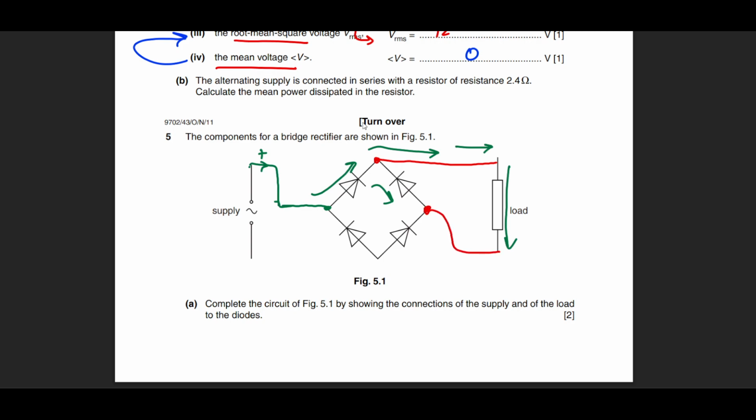So what will happen then? This current actually comes to this point and it repeats that same idea, that when the current was actually at this point, it had higher voltage. At this point, it has passed through the resistor. The voltage is low at this terminal. So the current cannot flow from a higher potential towards a low potential. This current will not be allowed to flow through this diode. I'm just complicating this situation so that you can try all the options before you finalize how to draw this diagram. So then I connect this towards this terminal, and now the current has a path to go through.